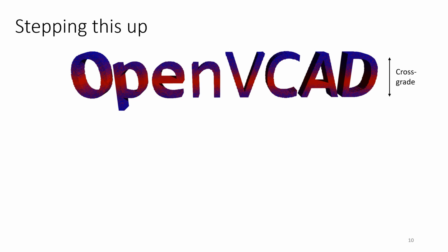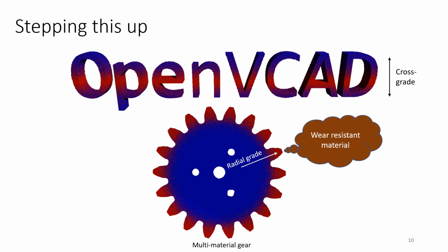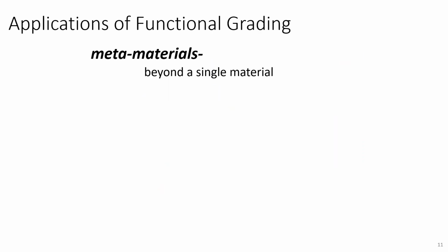So let's step this up a little bit. In my title slide, I showed this gradient that went across the OpenVCAD text. We could step it up a little more and make a multi-material gear. We can use other coordinate systems, so in this case, I'm using cylindrical coordinates. We're grading as we move out across the radius of the cylinder. Perhaps this has a mechanical motivation: a wear-resistant material in the teeth, but a cheaper and maybe lighter material in the inside of the gear.